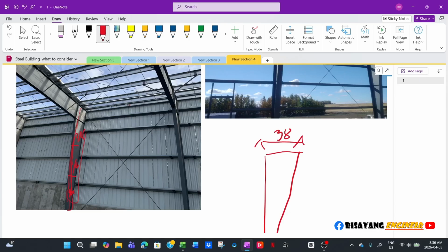It doesn't matter, it's still the same. But for the dead load, because I'm using a W section, it's just easy. Basically, all you have to do is select a certain section and assign it to the frame, and that's it. You don't have to model a non-prismatic section, which is more complicated.